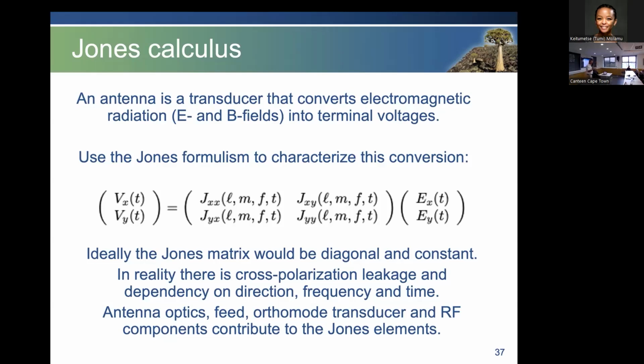In the elementary electronics courses, they talk about phasors. If you have a cosine signal, cos omega t, that's the real signal, then the analytic signal, or the phasor, is cos omega t plus j sin omega t, because sine is the Hilbert transform of cos. So there's no new information. You've just added it in.